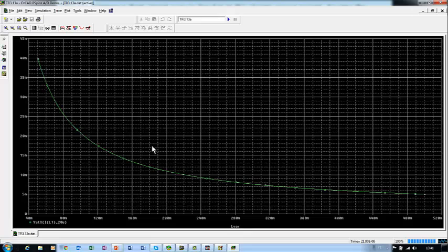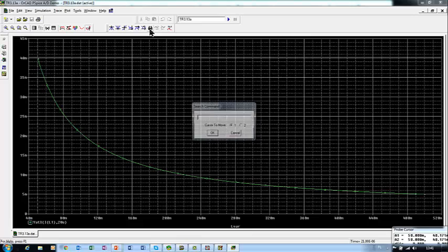That way, this is the plot of current, mesh current at 20 microseconds. We are looking for the level of 20 milliamp to find the proper value of inductance. We can do this by means of the toggle cursor and search for that level.